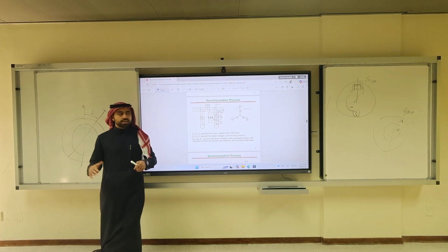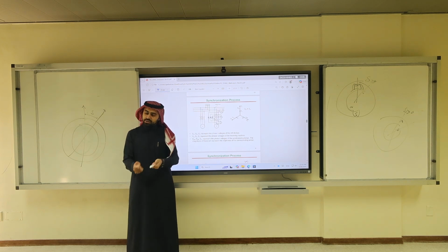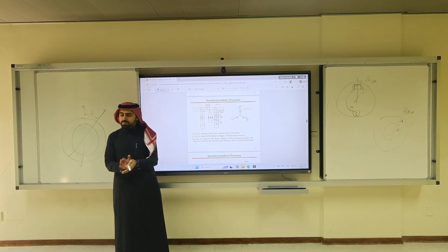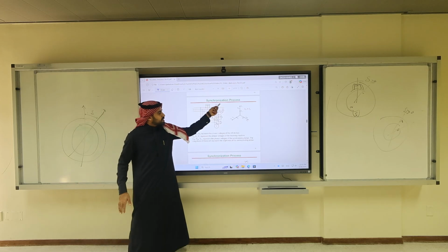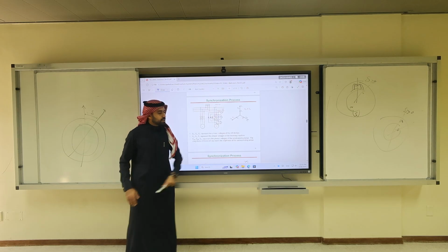So the power grid is like an infinite pool. If a synchronous generator tries to connect without synchronism, this synchronous generator would probably be driven out of the system and it will be damaged, but the grid will not be damaged because the grid is infinite bus. So be careful when you connect generators.